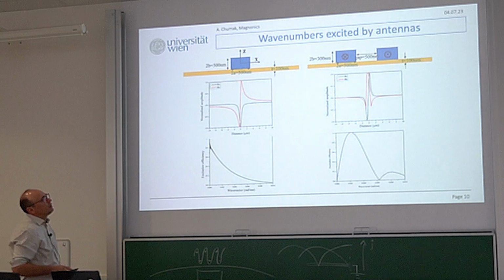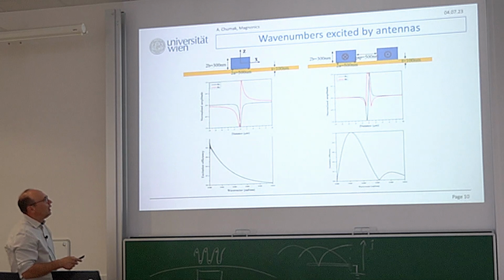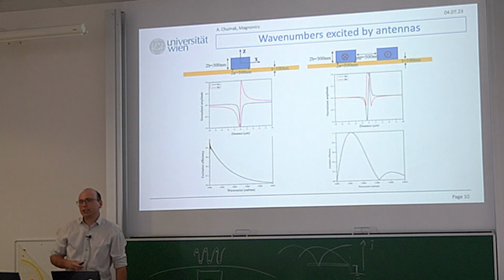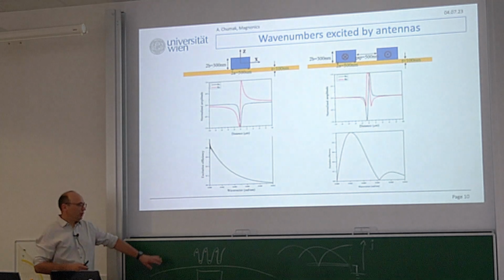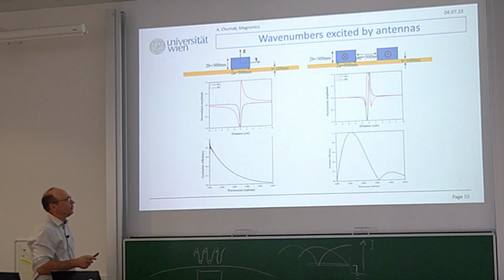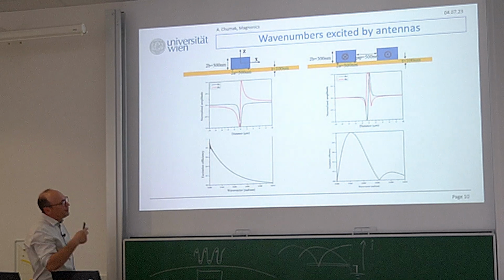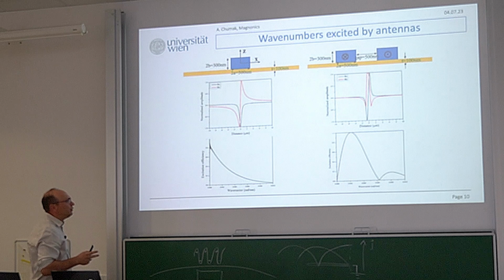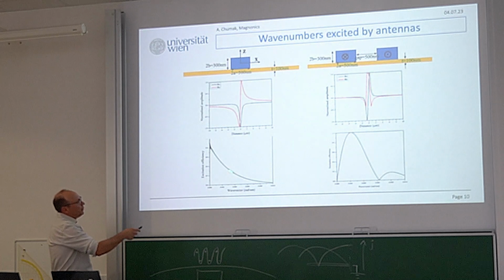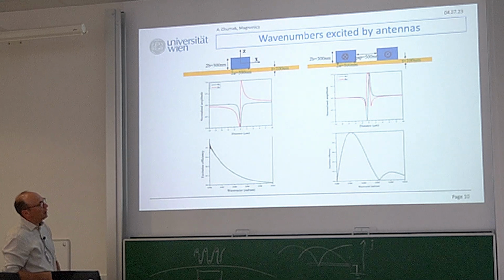But what you do afterwards, you just take the Fourier transformation of this field as a function of coordinate, and this will give you immediately the excitation efficiency. So that's what I have drawn here in a very kind of finger-like model. You can do it properly if you have the distribution of fields, and you decide which component will work for excitation for you, or you use both, and you do the Fourier transformation and you will get such behavior. And a decrease for a simple single strip line.